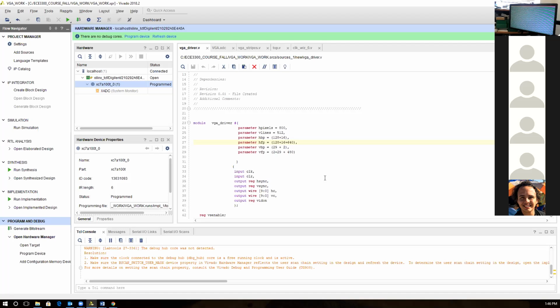Let's say I push the reset button. Look, boom, I reset everything. But because I reset and didn't enable these counters to give the order to send power to the screen, it started getting power again after the reset. But look how much time it takes. I push reset and look how long I'm waiting. It was a couple of seconds of waiting, right? There was a reason for this, coming from the division and reduction of the 100 megahertz to 25 megahertz.